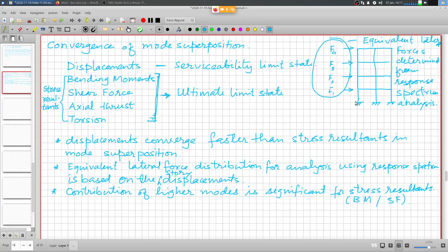After careful reanalysis of the complete system, it was realized that the problem was because the contribution of higher modes of vibration, where you have larger curvatures, leading to concentration of the stresses in upper floors, was neglected.